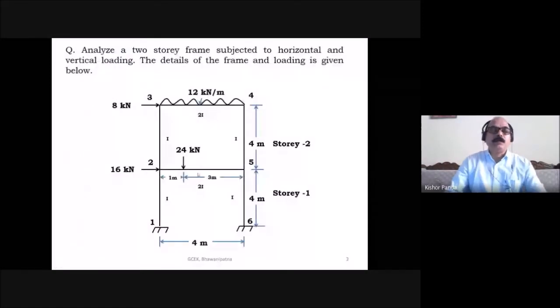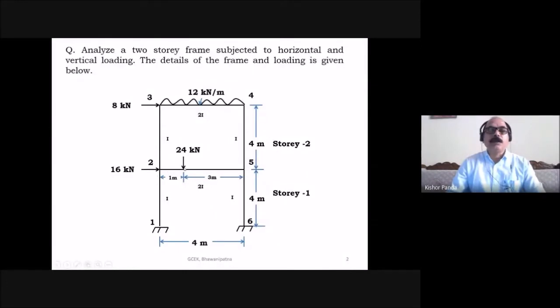So when we find out the rotational moments here, M-21, M-25 and M-23, you have to find out these 3 rotational moments. So what is the formula? When we find out the rotational moment of M-21, what is the formula? U21 into the sum of the far end rotation moments. So you have to take the far end rotation moment of this one, this one and this one.